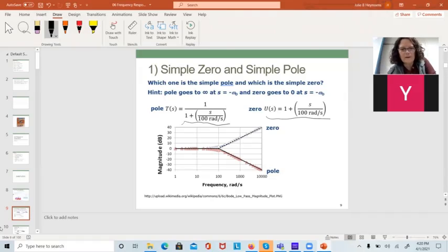If we plot them, what we get is this beautiful straight line approximation. When I get to whatever this frequency is here underneath S, when I put it in standard form, that is what I call my 3 dB frequency, because the gain is actually down by 3 dB at that point. But when we do the straight line approximation, we ignore that.